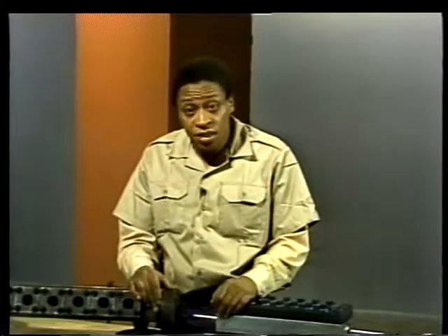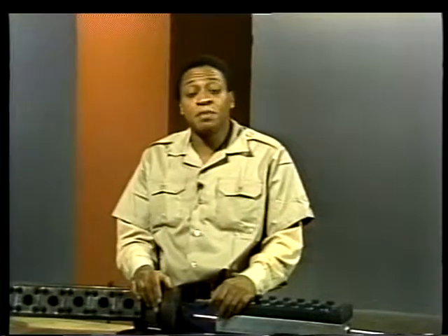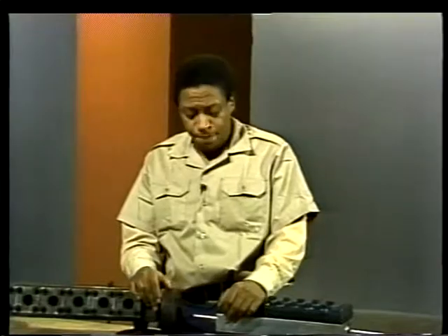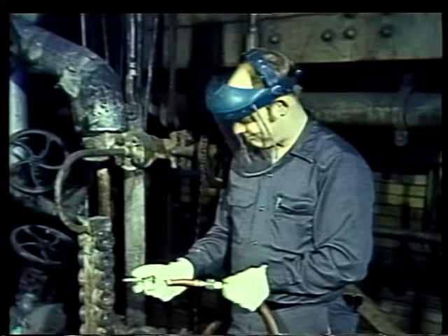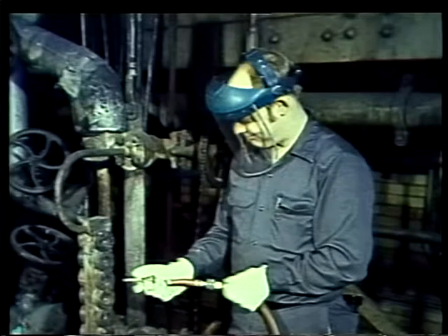A gauge glass gets dirty on the outside as well as on the inside. Gauge glasses should be kept free of dirt by periodically cleaning the outside of the glass. This can be done by blowing dirt off the glass with low pressure air. When you use low pressure air, wear eye protection. It'll prevent dirt from being blown into your eyes. Also follow any other safety precautions required by your plant.